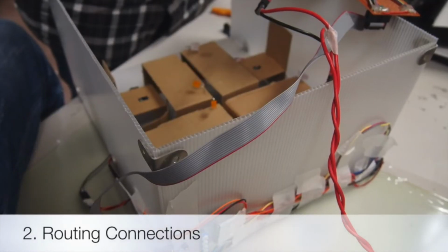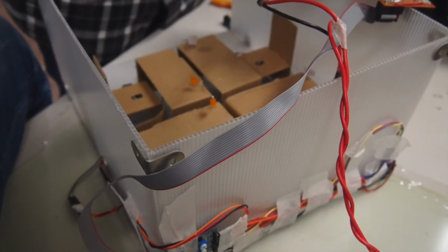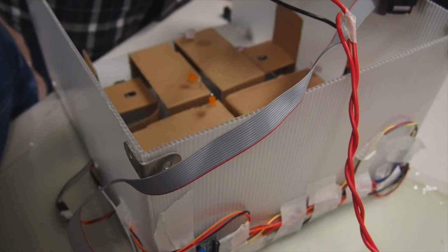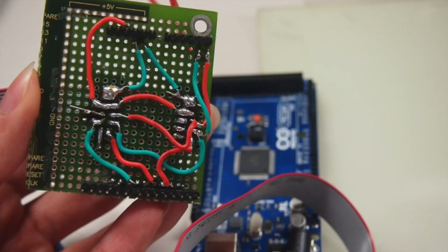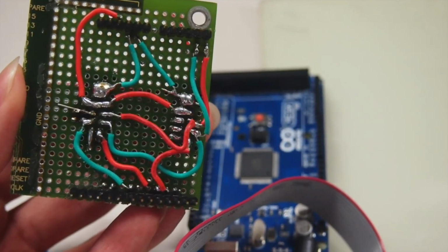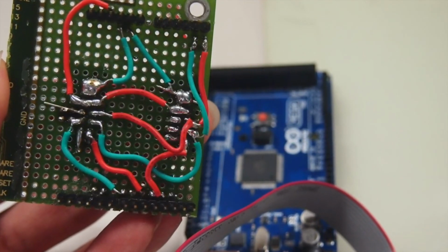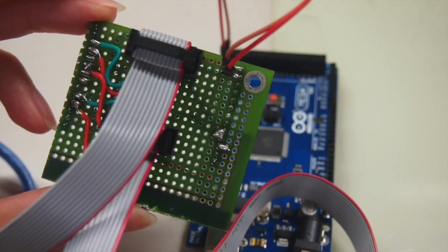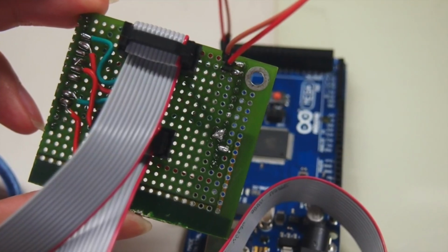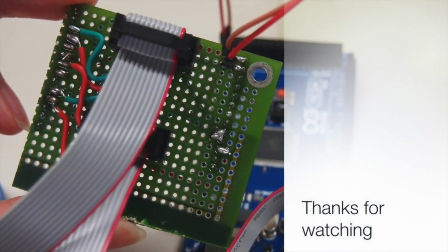Initially, we used a breadboard for the prototype of the electronic circuits. However, we found that wires are bundled together when the system gets more and more complex, and it is hard to maintain and it gets really difficult to troubleshoot and repair. Therefore, we started to organize the wires by making shields and PCBs. For example, we adopted a custom shield for the toilet system to fix the problem. Also, we modularized different parts of the system and used flat cables to connect between each other. We also designed some PCBs to eliminate the breadboard from our design. This solves the problem created from the bundle of wires.